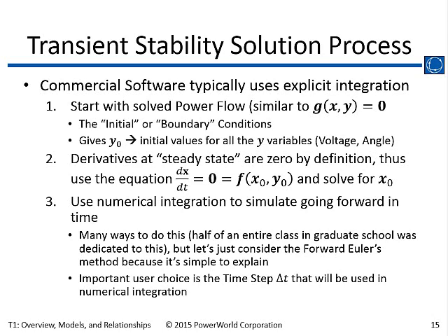The question was, power flow packages use positive sequence. How do you deal with imbalance when the system isn't really balanced, when it can't be modeled as a balanced three-phase system? How significant is that impact to the initial conditions? And how significant is the impact of the unbalance on the system? Power flow packages, most packages are positive sequence, so you're assuming a balanced three-phase representation. It gets unbalanced when you put a fault on the system.